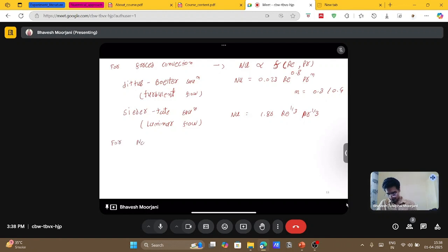If we are in natural convection, then the Nusselt number is related to the Rayleigh number, right? So it's shown as some empirical form of the Rayleigh number. Both the Reynolds number, Prandtl number, or the Rayleigh number in natural convection are fluid properties. So they depend on the fluid flow condition. If you see the equation of these dimensionless quantities, they are fluid flow dependent quantities. Either it will depend on the fluid property or the fluid flow conditions.